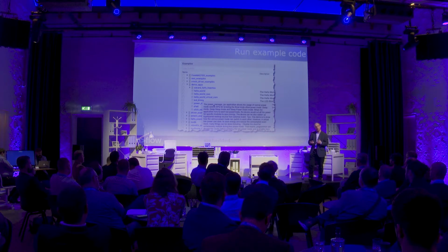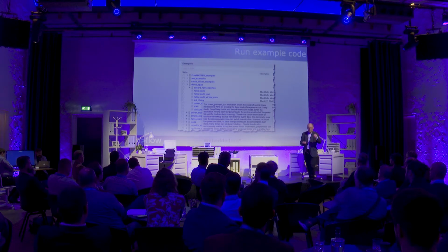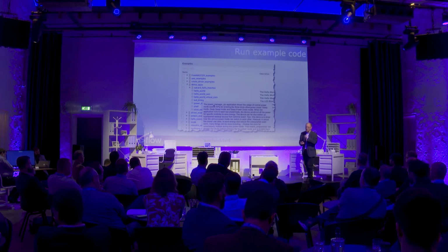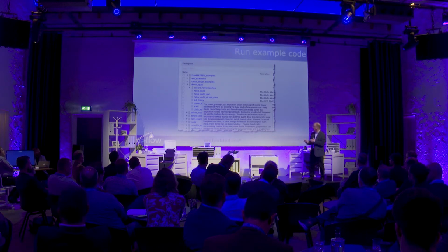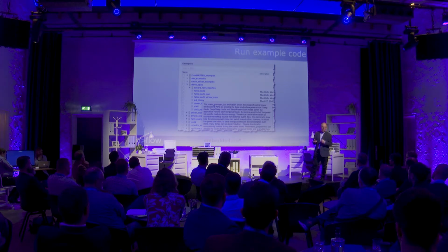So I would recommend that you or someone actually tests the microcontroller in a number of different use cases. Rent an environmental chamber if you need to, just to look at the realistic temperature profile for your system. And there should be a piece of software you can quickly run on an evaluation board to put the part into the different low power modes for you to actually go measure.